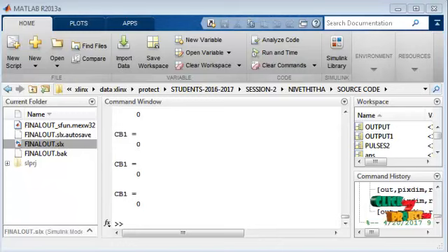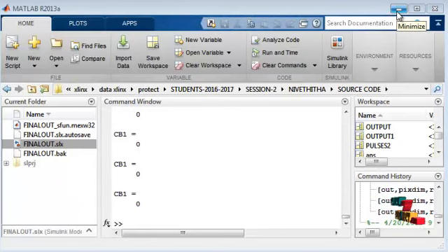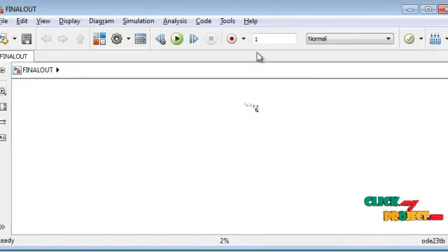Next we see the running process of our project. This proposed implementation is done in the MATLAB simulating environment. First open the MATLAB window and create a new model file. After creating the new model file, we arrange the elements as per the circuit diagram from the simulation library browser. In the library browser, various blocks are available. Our required blocks are in SimPowerSystems and commonly used blocks. From those blocks we get the elements and arrange the circuit as per the base paper. After arranging that, we click the run icon. The corresponding scopes show the corresponding outputs of voltage, current and such parameters.